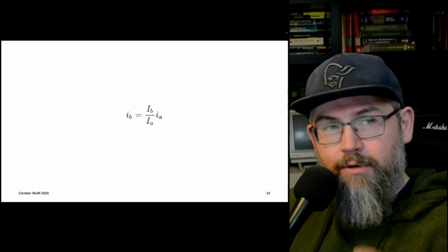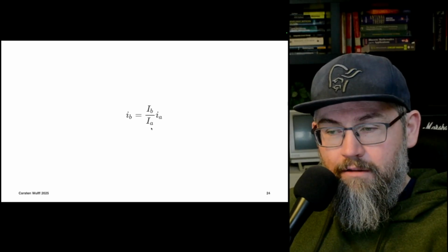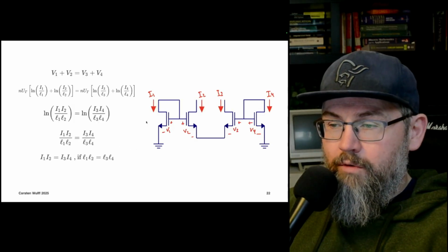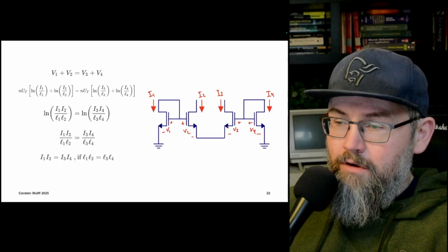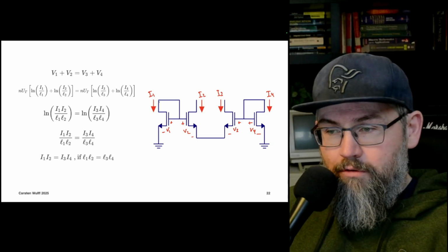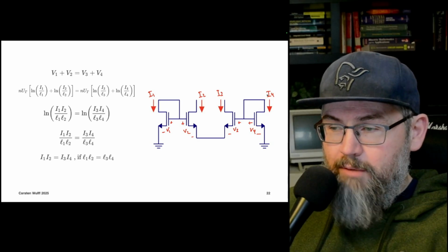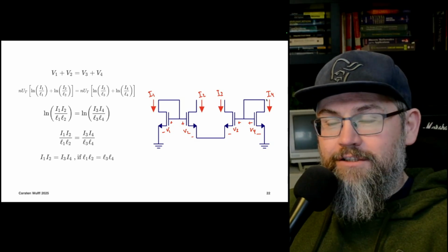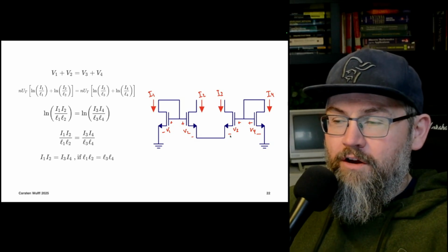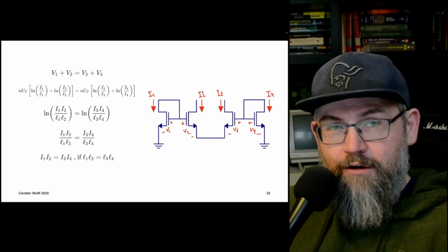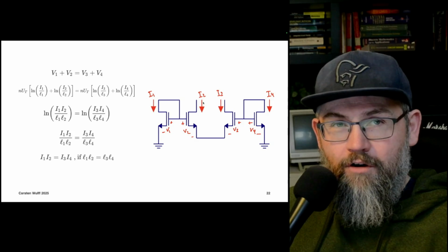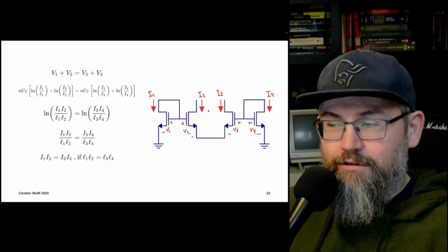And it's scaled by the ratio of the bias currents between those two branches. So if I'm looking at my system here, if I add a small current on one side, maybe at I4, then everything will arrange such that the current that goes out, for example at I2, is a scaled version of the input.